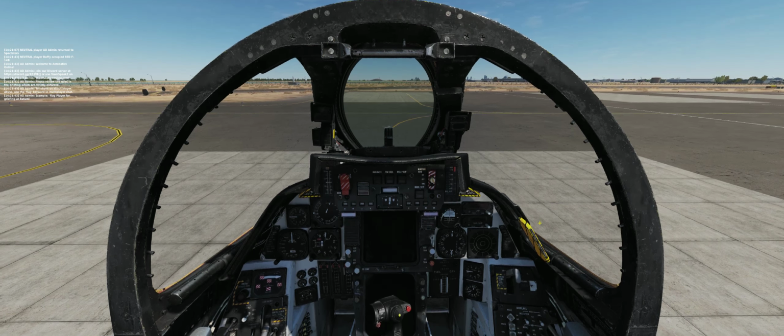Set gun rate, Sidewinder cool off, missile prep off, missile mode norm on ACM panel. Make sure emergency store jettison push light is out. Set air source to off. Set hydraulic transfer pump to off.